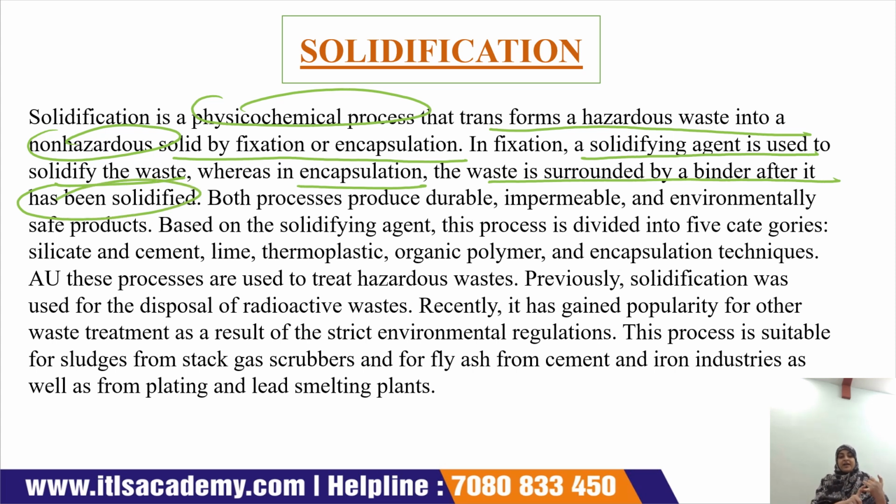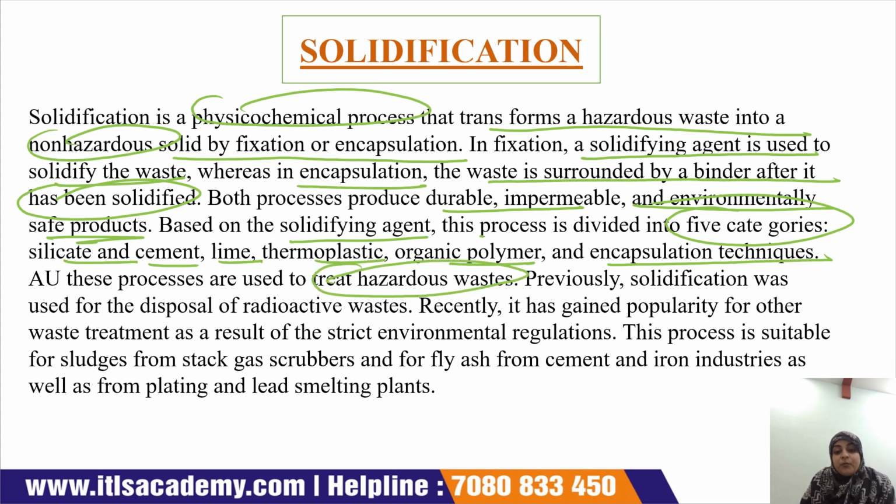Okay, so in fixation we use a solidifying agent so that it will solidify the waste, but in case of encapsulation the waste is surrounded by the binder, and this binder solidifies it. Both processes give durable, impermeable and environmentally safe products. Based on the solidifying agent, these processes are divided into five categories: silicate, cement, lime, thermoplastic, organic polymer and encapsulation technique. And these processes are used for the treatment of hazardous waste.